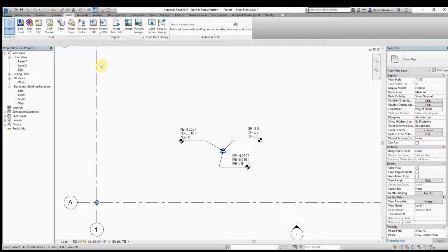So theoretically, what I would suggest is you import it into a Revit file, and if there's another survey plan, then you can also import it and keep it, and basically link this Revit file in to work from. It works pretty good.